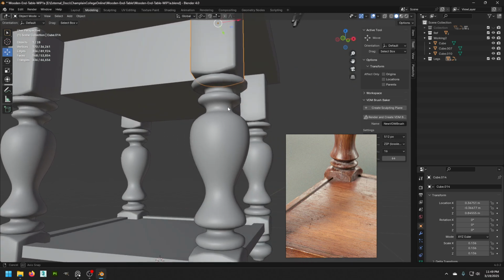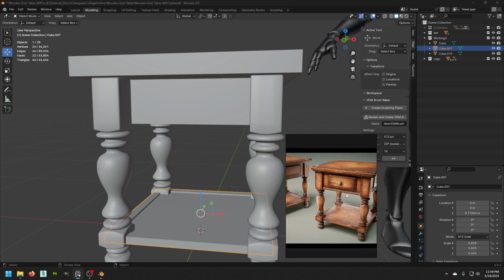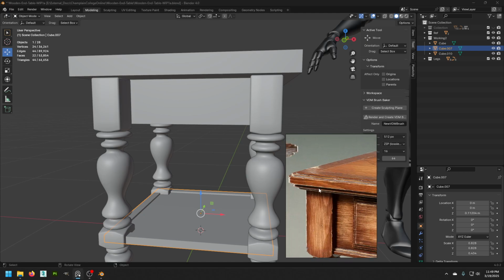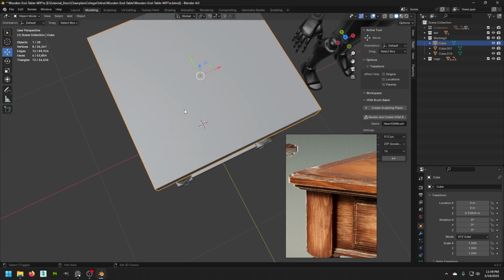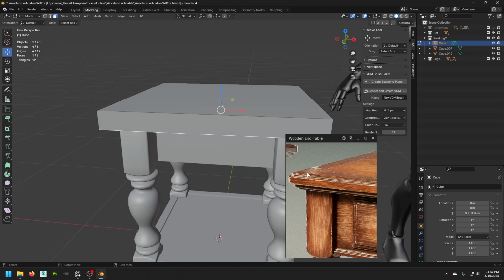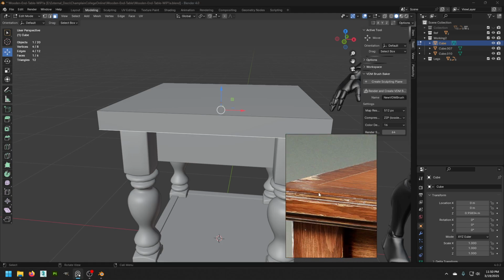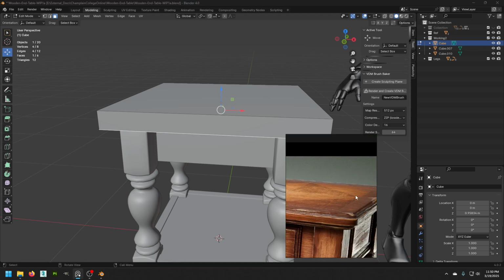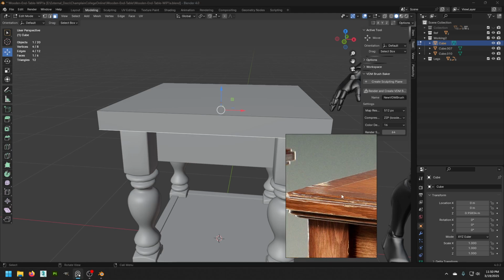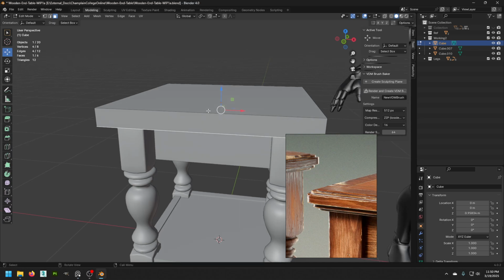Okay, that piece is good. We'll do a little bit more refinement on this top piece here, and then I'll probably take another cut and then do the last piece. Similar thing here. We have these edges that are inset and then extruded out, and then a little bit of bevel. On top of this, we also have this pattern as well as this small edge here that is inset. So we're going to add that in there.